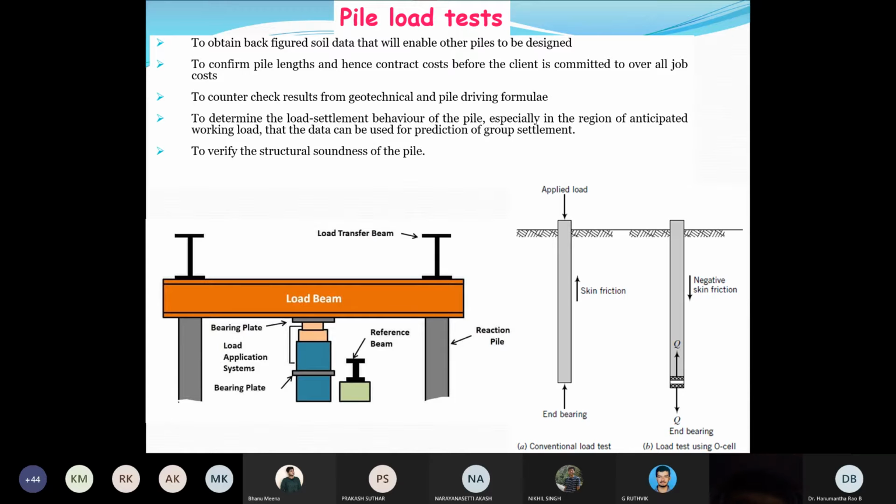This is a big challenge. As a geotechnical and civil engineer, you need to understand that nothing is visible at the bottom. We do not know what is happening. We do not know whether we are covering the reinforcement or not. And if there is water inside, then how do we lay the concrete? So there are several challenges in pile foundations.